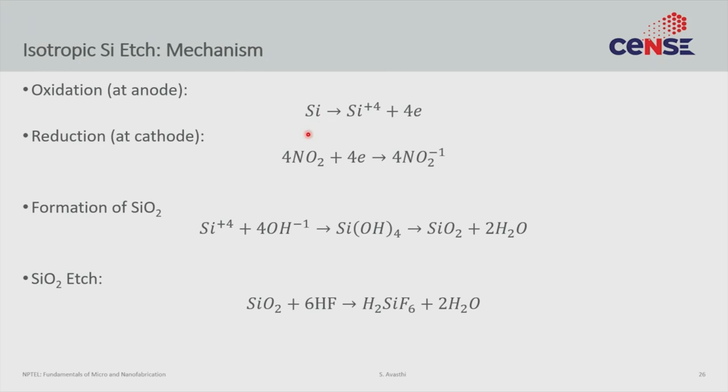So the intuitive understanding of the mechanism that we started with in the first slide was not too off, right? Overall, what is happening is that the exposed silicon is getting oxidized with HNO3, specifically NO2, not HNO3, but still because of HNO3's presence. That silicon dioxide is then reacting with hydrofluoric acid to get etched away. That exposes fresh silicon that can once again react with the HNO3.